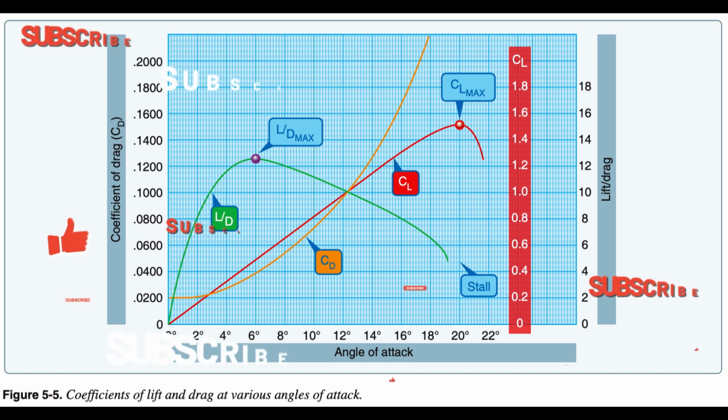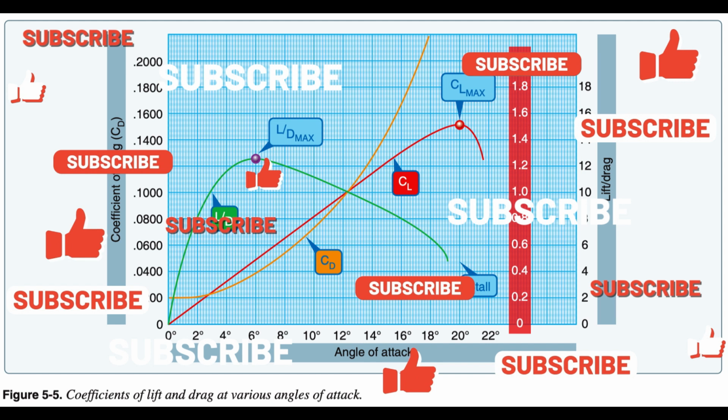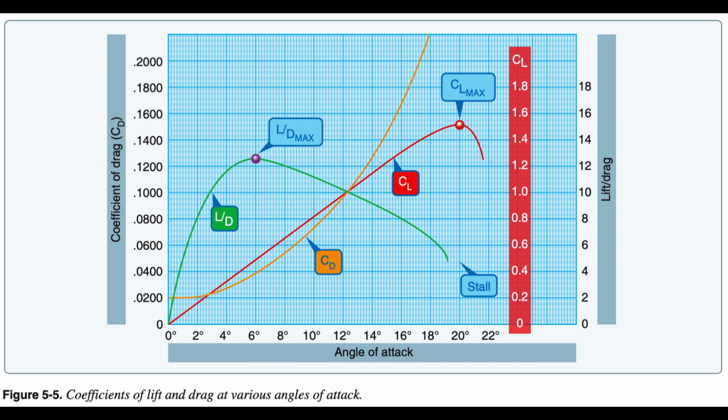In unaccelerated flight with the lift and drag data steady, the proportions of the coefficient of lift, CL, and coefficient of drag, CD, can be calculated for specific AOA. Figure 5.5. The coefficient of lift is dimensionless and relates the lift generated by a lifting body, the dynamic pressure of the fluid flow around the body, and a reference area associated with the body. The coefficient of drag is also dimensionless and is used to quantify the drag of an object in a fluid environment, such as air, and is always associated with a particular surface area.